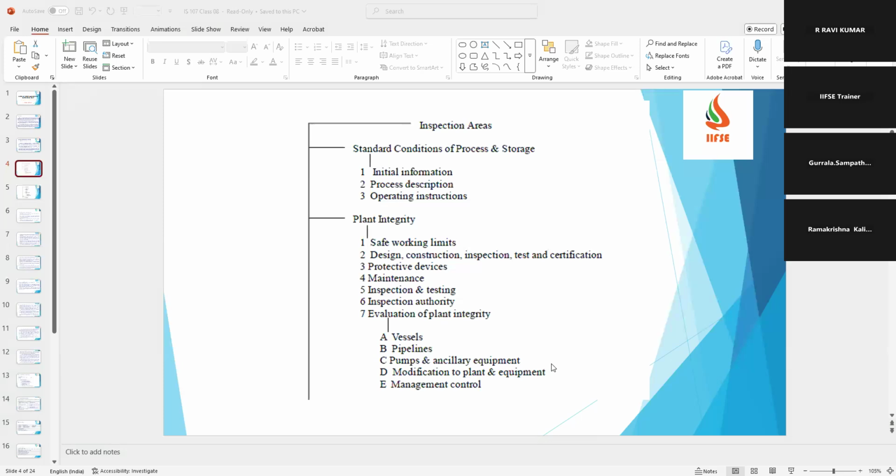Management of change request. In organizations they call it management of change request. So when any modification happens, they do a study for the modification, then they create a MOC. Accordingly they make the changes, the changes are informed to all the respective people, and those MOCs are also authorized or certified by the top management.